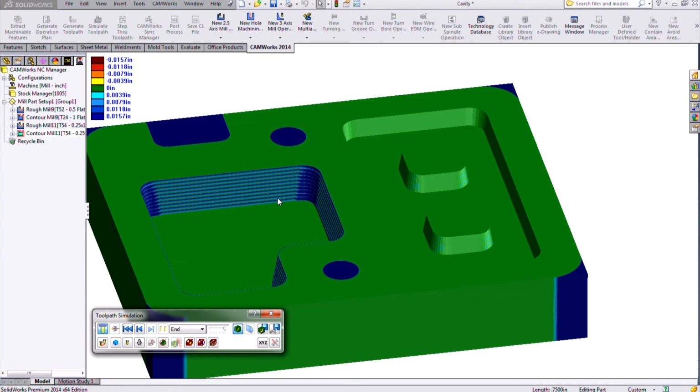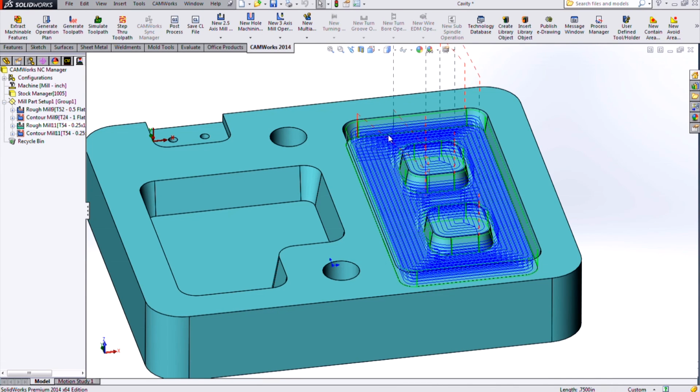So using the tapered end mills, you just want to remember to program, in this case, based on the bottom loops of your pocket, and make sure that you're not double compensating by leaving on something like auto detect or specifying a taper angle in the software.